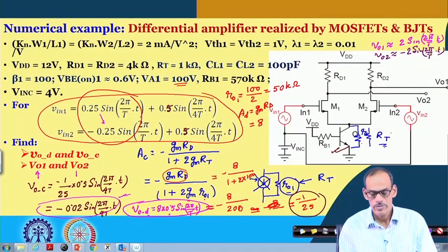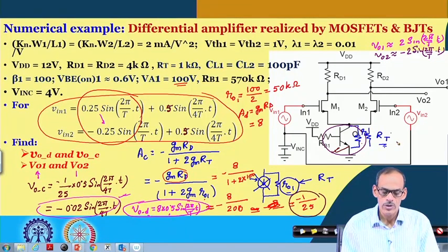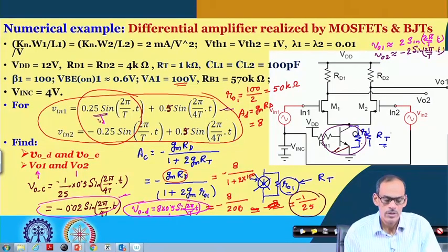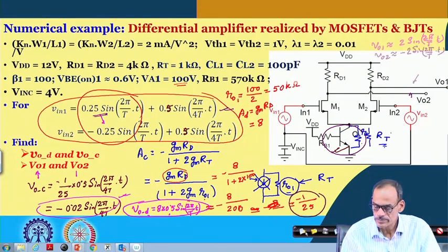So, to summarize, replacing this tail is also helping to suppress this common mode part and still maintaining the differential signal quite prominent. Particularly if you observe the output signals there, they are almost complementary to each other.